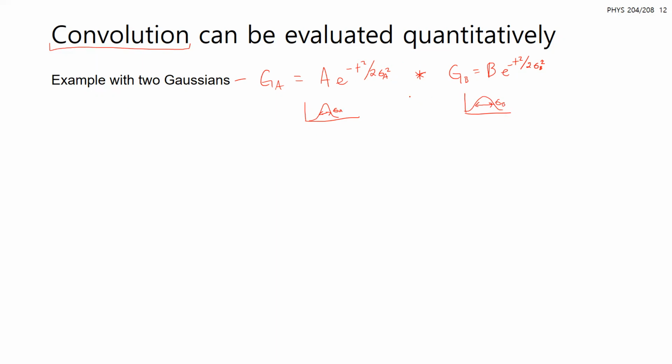And if we want to convolve these two Gaussians, we can do the whole integral that we wrote out and evaluate that. But if we remember back to what we defined, that if you're taking two functions and you're taking the convolution, it's equivalent to taking the Fourier transform and multiplying the Fourier transform of those same two functions in the frequency domain.